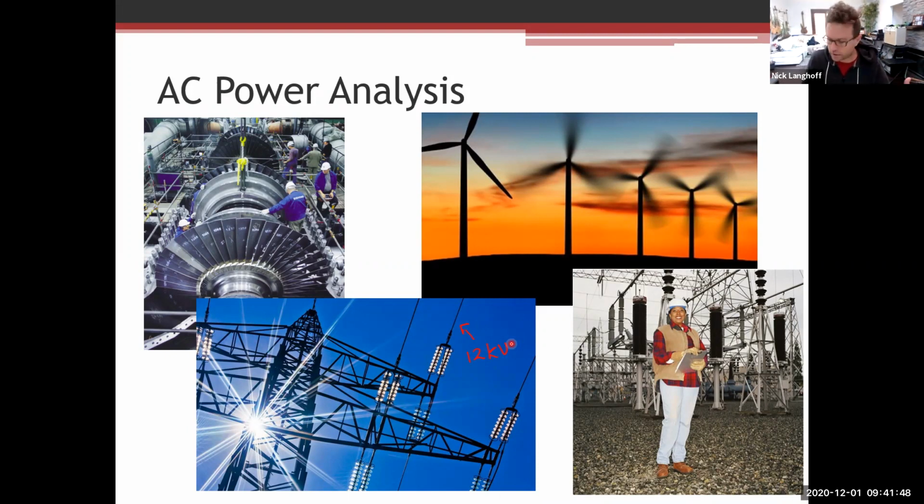And to get back to my point of why power is transmitted as AC, it turns out that because of the way induction works, you can't put DC through a transformer. There's no changing magnetic field, and it doesn't induce any energy in the next coil.